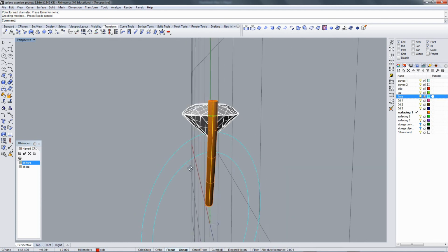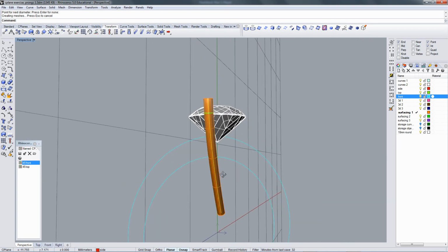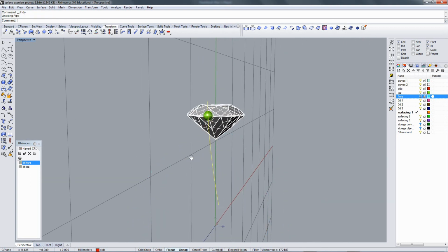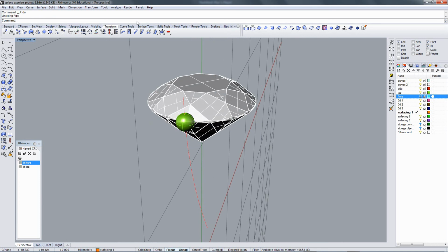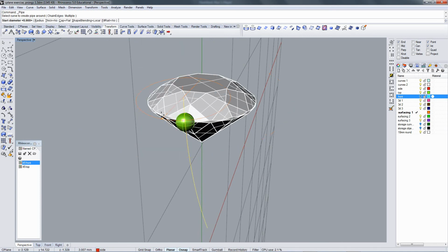I want to keep in mind where the ring bore is, because I'm going to lose all of this. That's not much of a taper. I'm going to taper it more. So start diameter I want to be 1, not 0.9. Remember, Rhino can start this from either end, so always double check your command line. I want 1.